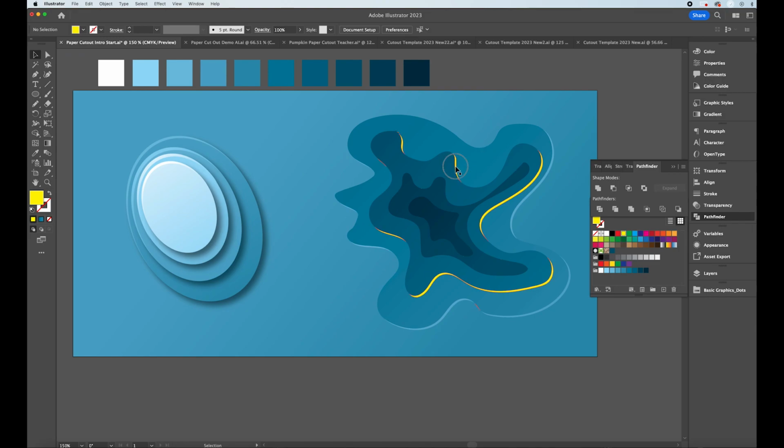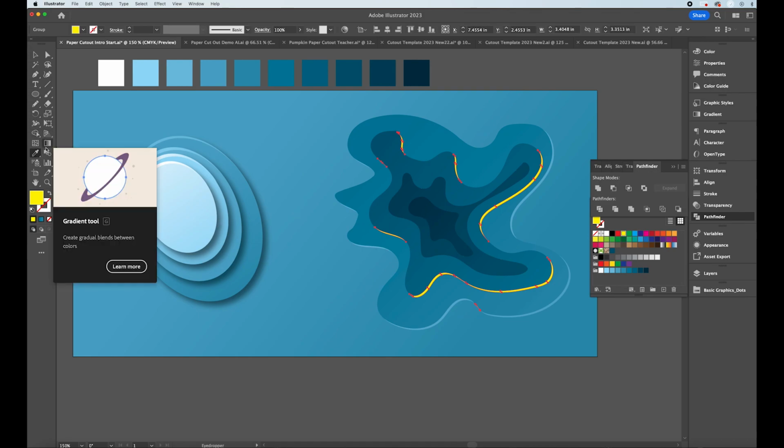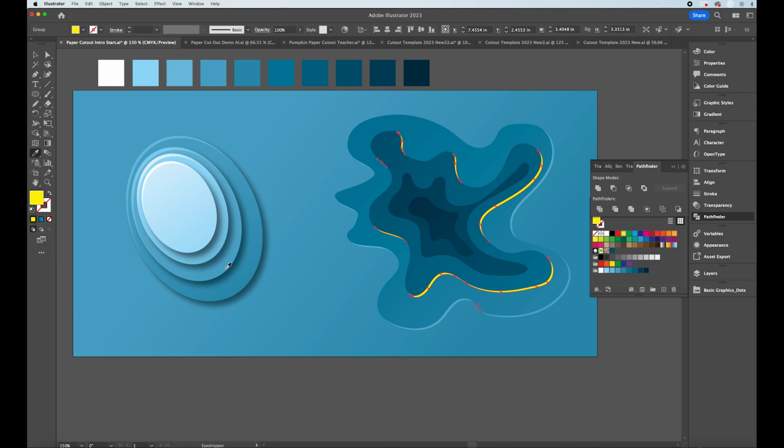So with these yellow pieces remaining, again, I want to create a highlight. I can use the eyedropper tool to match to, again, another gradient. Or picking out the gradient from above, we can modify the gradient so it travels and creates a highlight on those features.